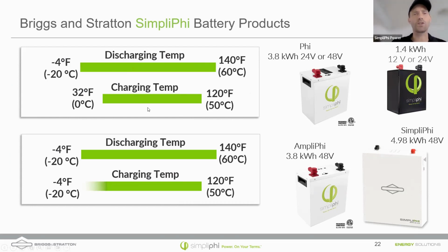If you are charging in really low temperatures, you want that inverter or charge controller to heavily curtail the charging rate. We recommend no more than a rate of C/20 if you're charging below 0 Celsius. So it's imperative that you pay attention to these parameters. And one of the things you can do to prevent your batteries from being in ultra low temperatures, remember this is the battery temperature, it shouldn't be below 0 during a charging cycle.